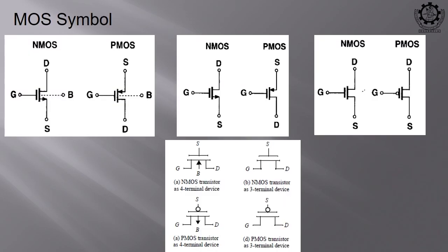So, that was our diode. Now, let us come to the MOSFET, and I hope you all know the symbol. There are several symbols. For digital circuits this symbol is quite popular: the NMOS is without any bubble, and for PMOS there is a bubble at the gate, or we have an arrow. For NMOS the arrow is from the channel towards the source, and for PMOS towards the channel. We have a fourth terminal, that is the bulk terminal. Sometimes we use an arrow for this bulk terminal, or sometimes without any arrow.